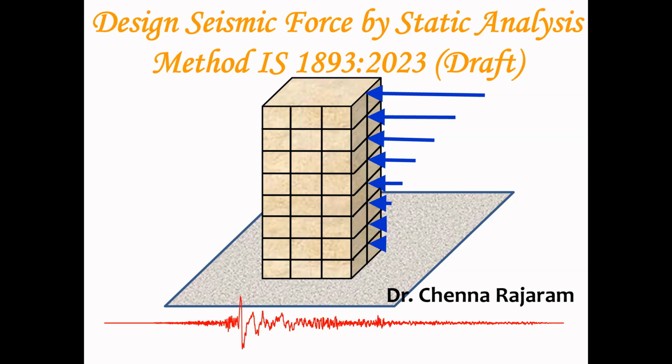Today's topic is design seismic force by static analysis method as per IS 1893 2023 draft code. In this video, I am going to explain the procedure how to calculate the lateral forces like base shear, story shear, and distribution of story shears onto frames using linear equivalent static analysis method. Before that, we would like to understand what is the earthquake design philosophy.